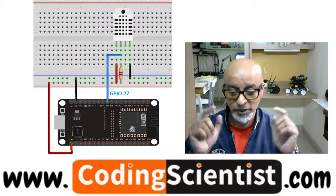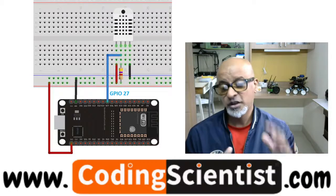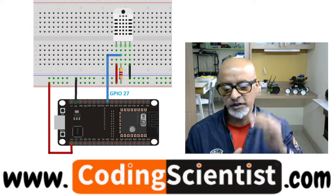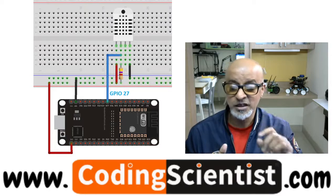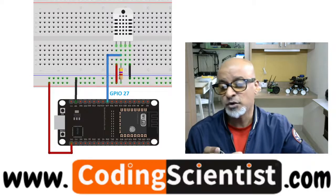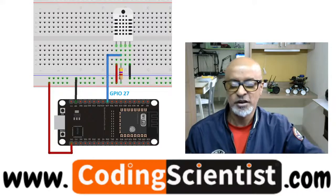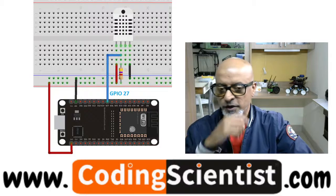You can use this particular circuit drawing for DHT11 or DHT22 sensors. The code will remain the same. The web server code which is written in C++ remains the same. There are no changes, unless you change the pin from GPIO pin 27 to any other pin of the ESP32. Then you have to go to that section and declare which pin you are triggering. So that's all you've got to do. All right, so let's take a look.